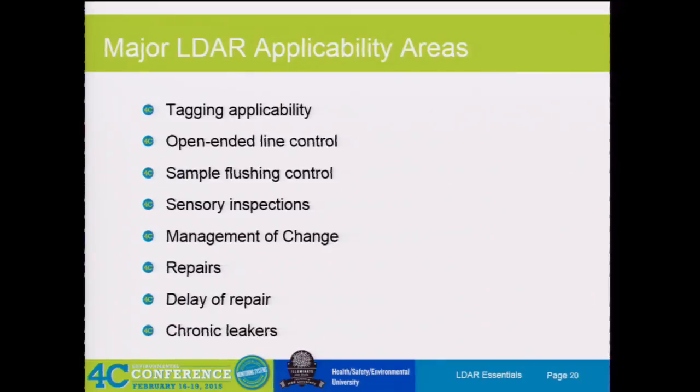Delay of repair. How many folks can just put something on DOR here? You can just say, oh, that component's going to go on delay of repair. Okay, so with that, DOR is basically a license to leak. And so what we recommend is have more folks than just one sign off on it. I don't know if you guys have ever heard the story, and it's actually not a story, it's a true piece. There was a site, and it was a one-man LDAR technician.